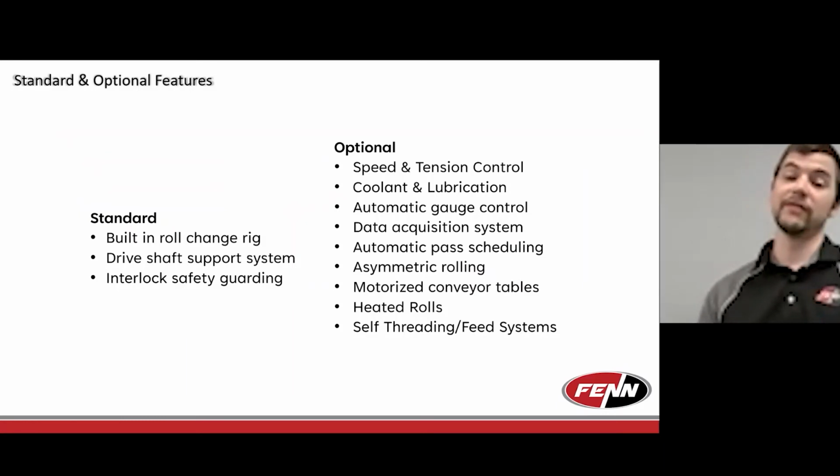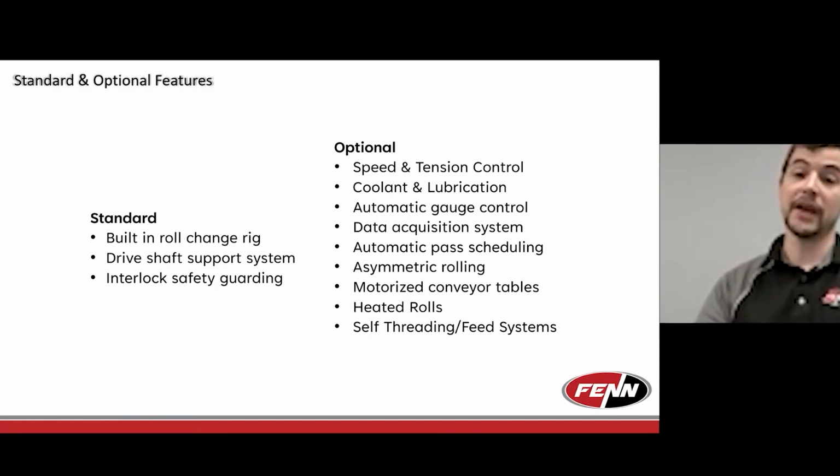The other types of features, which we've listed here on the right side, there are many applications, and some I would say are used with high frequency, more often than not, but depending on the application needs, they're not always definitively provided. So anytime we're running continuous coil, like I said, speed and tension control immediately becomes a thing that we provide, where we're trying to balance the speed of every motorized device, every reducing device, taking into account things like material elongation and maintaining a proper controlled tension so that we can get the best quality of material and reduce things like, as I mentioned, bowing and camber.